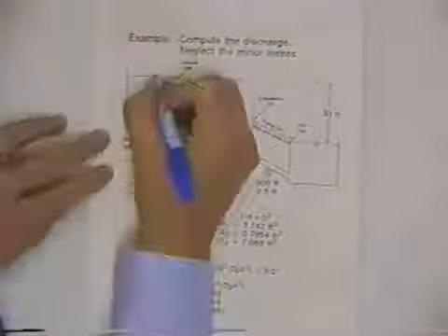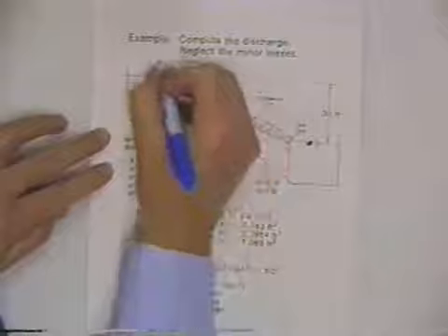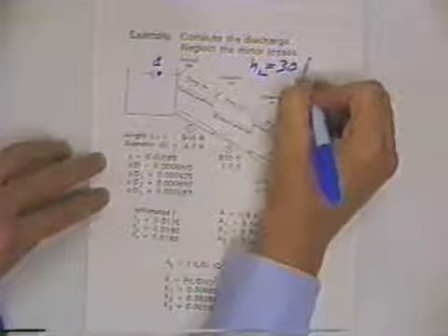We're going to use the energy equation, although in the problem I didn't even bother to write it out because we've done this before. If you pick two points, a 1 and a 2, and write the energy equation between them, you always come out that the head loss is equal to the difference in the water surface.